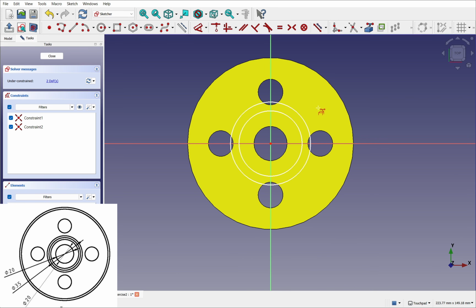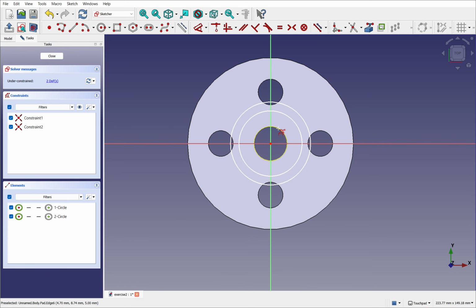Once we selected that, you'll notice that when hovering over the feature, we get the edges and faces highlighted. This is the pre-selection. If I hover over this internal edge, we see it's highlighted. If I click once, it imports that geometry in, and we can see it in purple on the left-hand side here. This is external geometry. Let's right-click to cancel the tool.